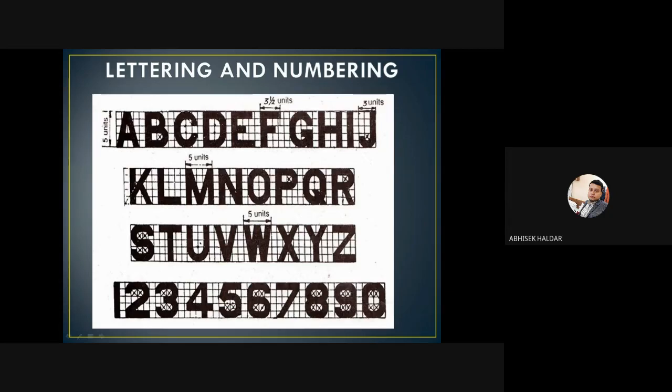But the two lines, the topmost line and the bottommost line you draw, should be very thin. I may not see that, but you can see that. So that is for your reference, so that whatever space you have in between should be equal, provided these two lines are parallel. So that is my main goal in this slide, to make you understand that whatever you need to write in your drawing sheet, always try to use pencil and use capital letters, and all the capital letters should be of the same size.